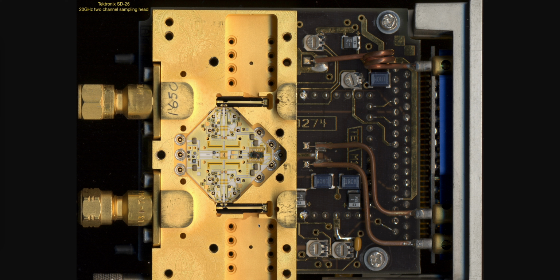We can see that this head was prepared for that but didn't equip TDR, and with dual heads and TDR we can measure impedance of circuits, of transmission lines, differential transmission lines, and this is why those dual heads are very sought after.